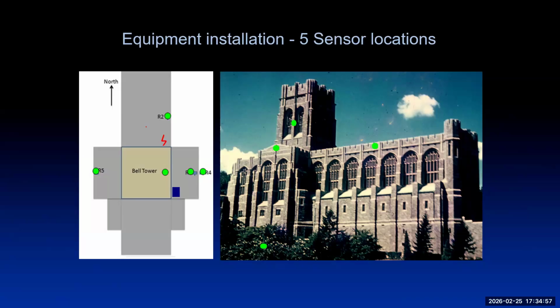So under that circumstance, we saw that the nave was swinging around, the transepts had their own vibration frequency a little bit, so the interface between the transepts and the nave were where we thought cracking must be occurring.